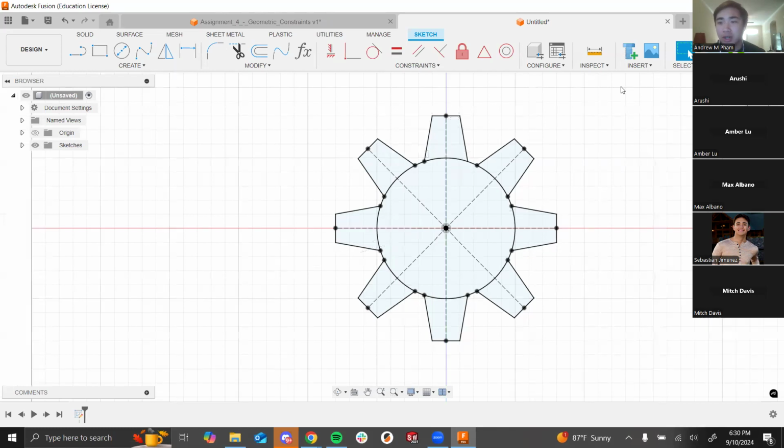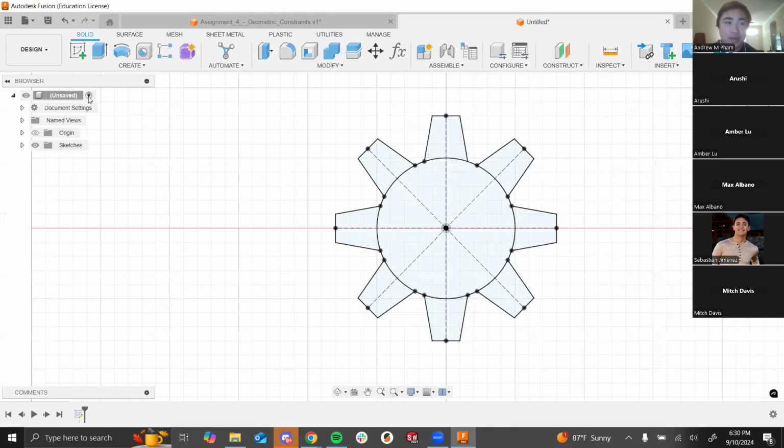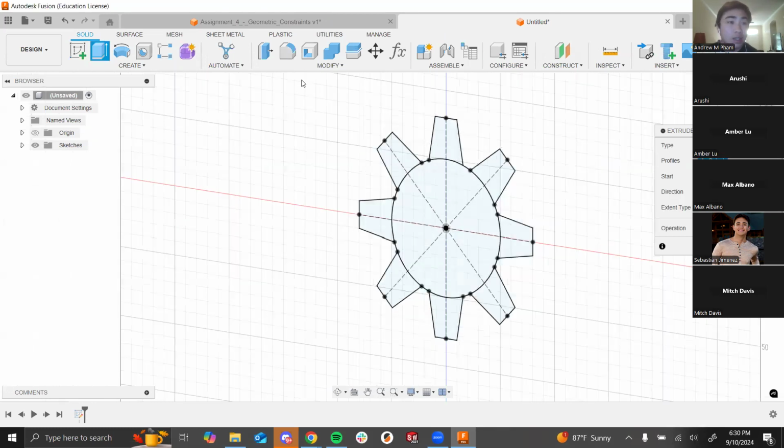Okay. I'm going to finish this sketch here, and then I'm just going to extrude it. So up here in the top right, I'm going to finish it, and then I'm going to extrude it like we've done for past objects. You can see that it hasn't auto-selected anything, and that's because there's multiple closed bodies here. If you wanted to, you could have gone into the sketch and trimmed each little arc in between each tooth, and then it would have auto extruded.